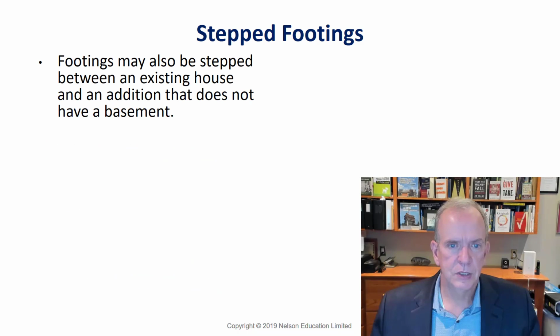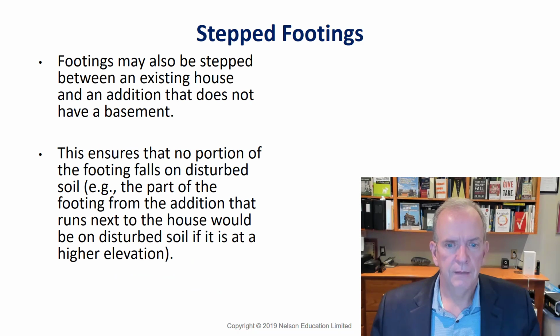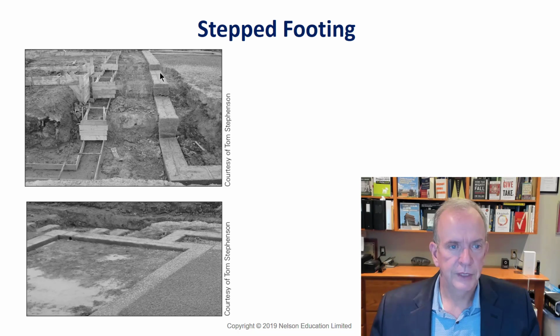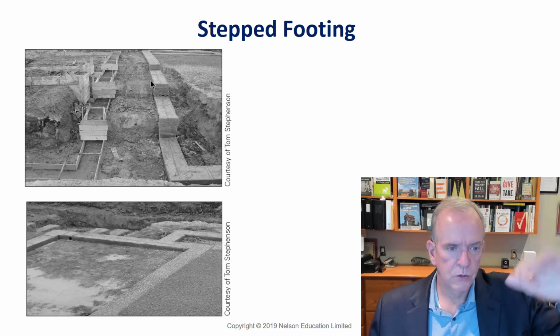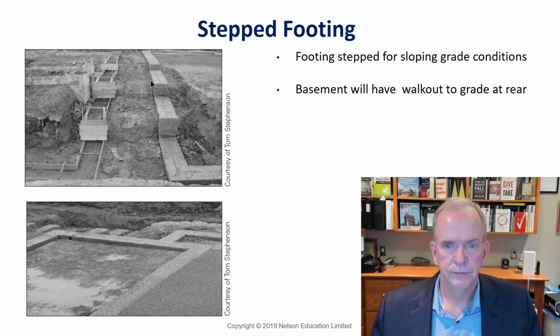So step foundations kind of look like, let's see, like this, steps. There's minimums and maximums that the building code has for the size of the steps. They don't want them too deep. I'd have to look that up right now to be sure, but I think it's 600 millimeters. So you can sort of see, this has a sloping grade, this particular house.